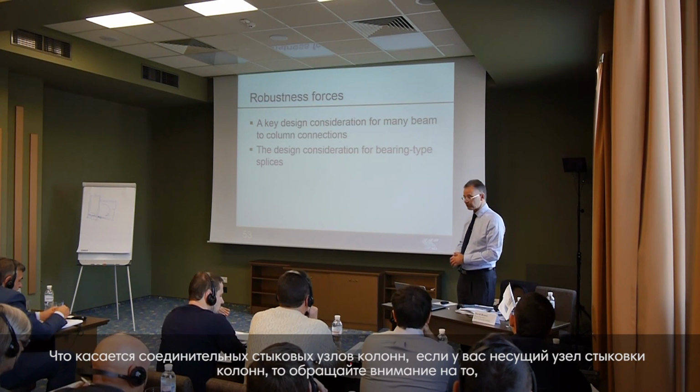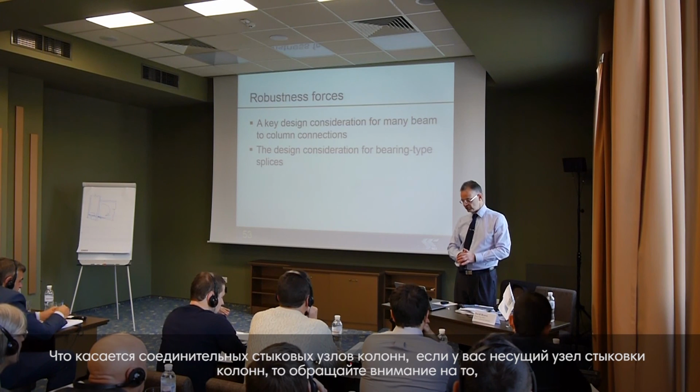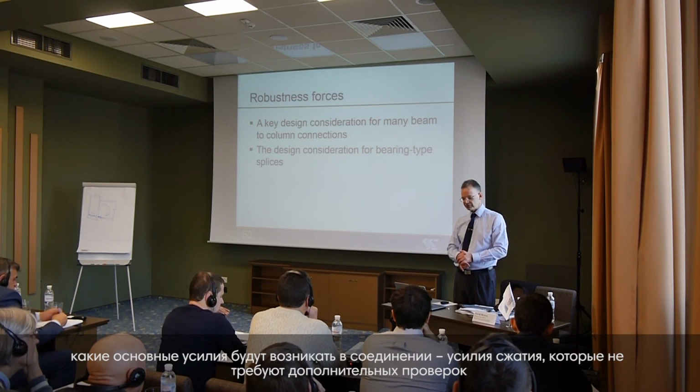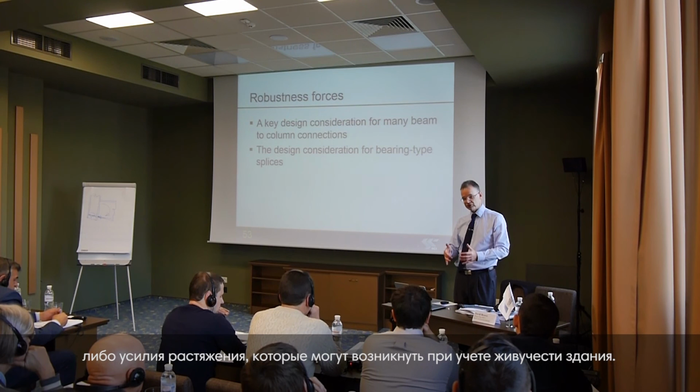In terms of splices, if you choose a bearing type splice, then in compression there is no design requirement. The design requirement will be the tension force which arises due to the robustness rules.